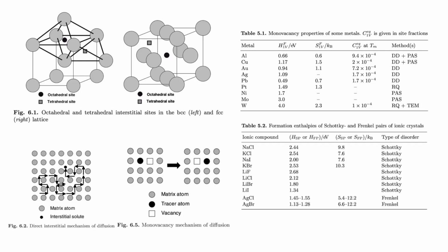These are the experimental techniques which were used to measure this, most likely, and nowadays mostly it's done with PAS, positron annihilation spectroscopy, because basically you generate a nuclear reaction to create positrons, and when it goes into the structure with a defect, it gets annihilated, and then we know how many we have and how fast they get annihilated.